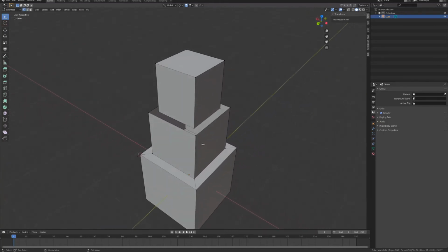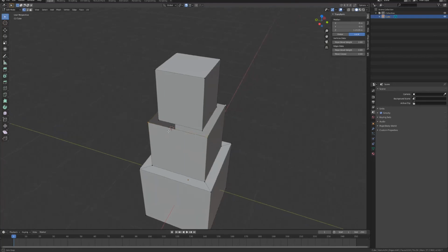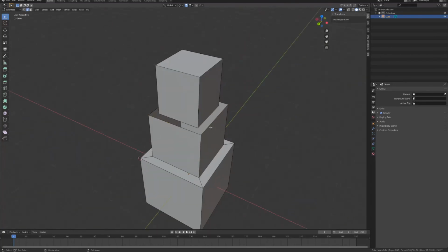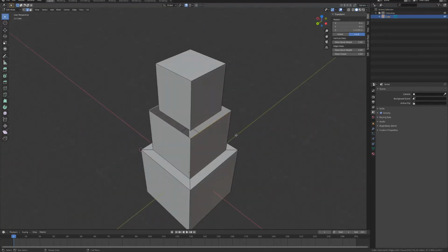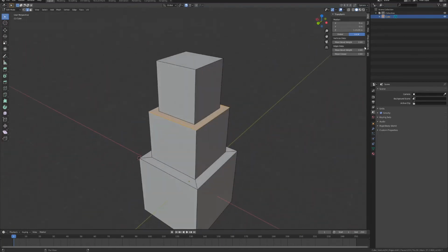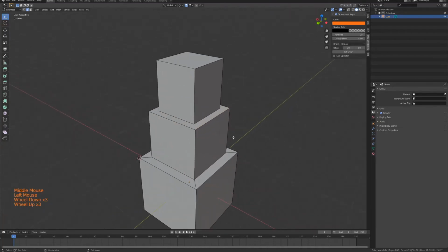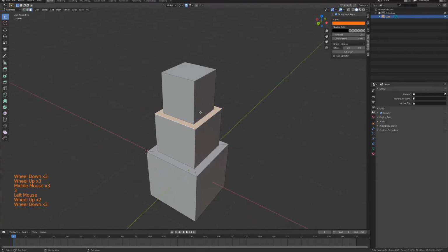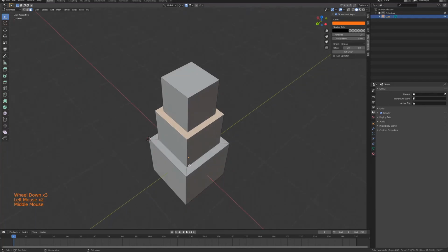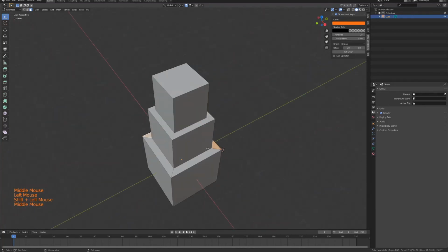Now, you can select the 4 vertices, or you can do pretty much the same thing by selecting 2 edges that also share an edge, and then you can press F. Also, apparently my screencast has decided not to work anymore, which is fun. So that will now create a cube, or a square, and no extra geometry will be used, which is very nice for optimization.